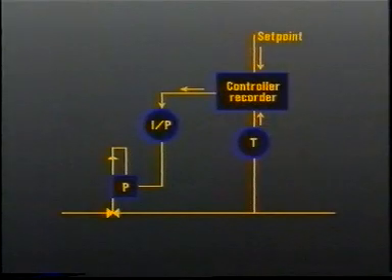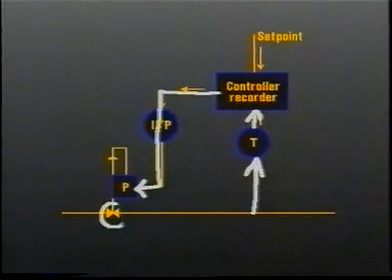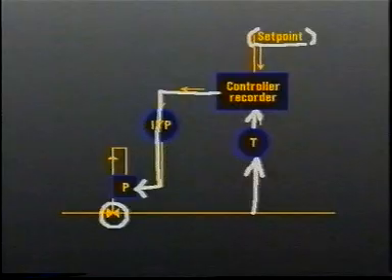It follows then that closed loop control is usually implemented through the use of process feedback. Here a controlled variable is measured, and that value is then used to generate a control signal that will change the process input in a way that will maintain the process at or near its set point. You can see why closed loop control is normally referred to as automatic control.